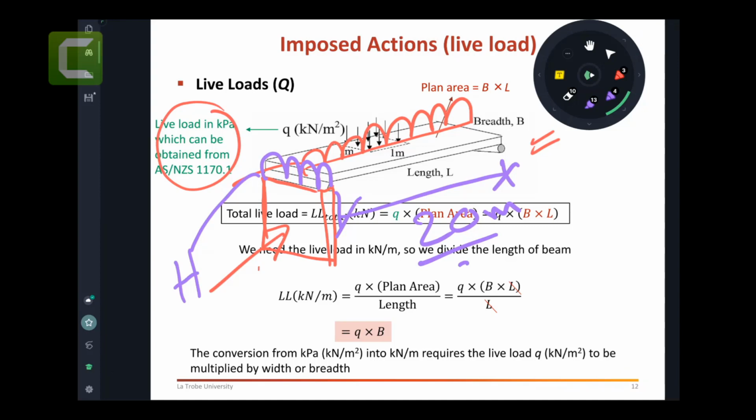Okay, well, thanks for trying. But when you say 20, that means you are ignoring this side. When you say 20, you are saying the whole span is actually carried by this poor guy. But isn't someone else here carrying it? So do you want to change your mind here? So would it be half the length? Correct. It will be half. It will be 10. And that 10 is the floor load width I'm talking about.